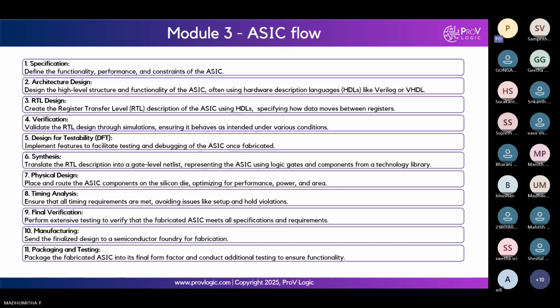And if you're going to develop an IC for a laptop, considerably the size can be bigger. Now, this is called a constraint. Constraint of the IC means conditions, as in these are the conditions of the IC, and when we are doing our physical design for the IC, we should not go beyond these constraints. We have to adhere to these constraints. So area is one such constraint. Next is frequency of the design. If the client says the IC which is going to be designed must operate at 1 gigahertz, then what is the time period of that IC?